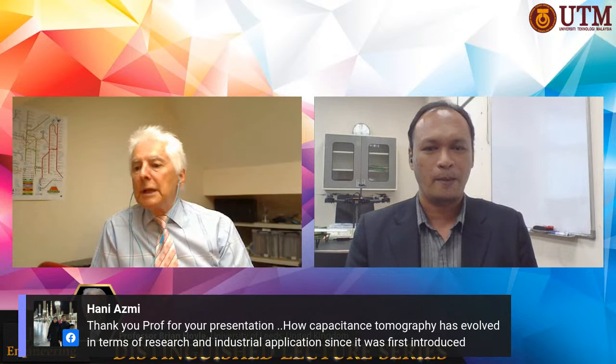Well, I think there's been lots of capacitance work around the planet. We have lots of resistance and impedance work as well. But capacitance is very useful for oil flows, where we're looking very much at dielectric materials and not conductive ones. We're looking now at very advanced systems, which can actually detect very tiny amounts of permittivity change.